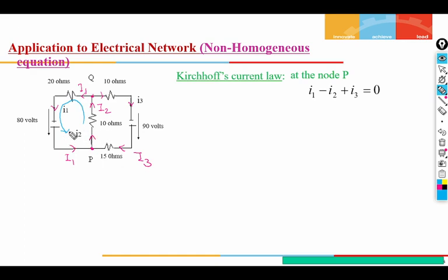The benefit is that when the direction of the loop and the direction of the voltage are the same, we consider plus E as a whole; if opposite, we take minus E. Also, when the direction of the loop and the direction of the current match, the voltage drop is also positive.